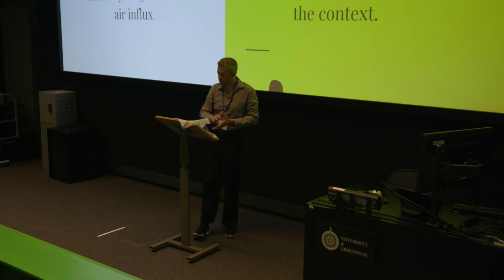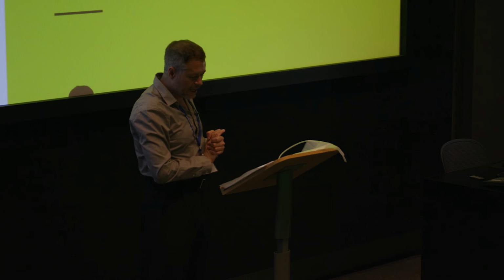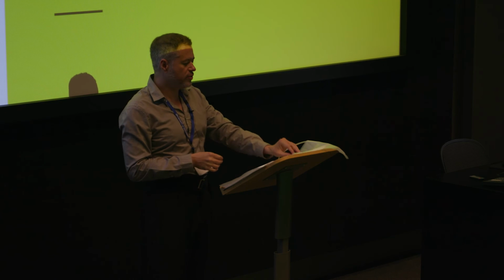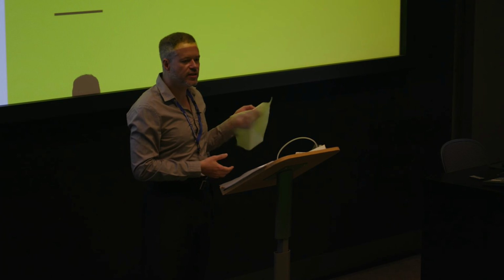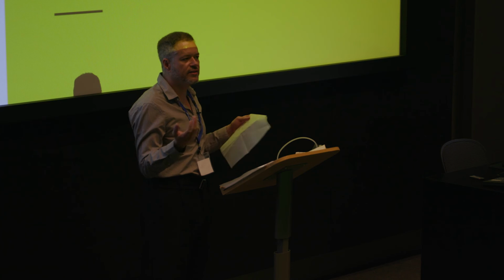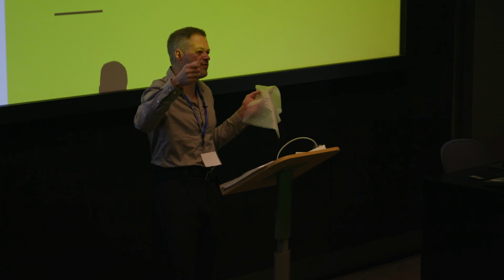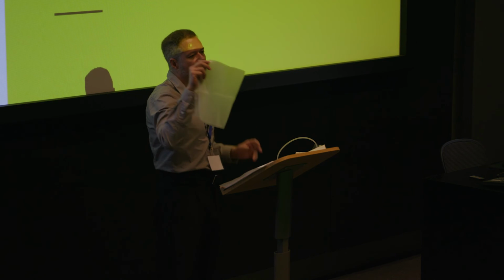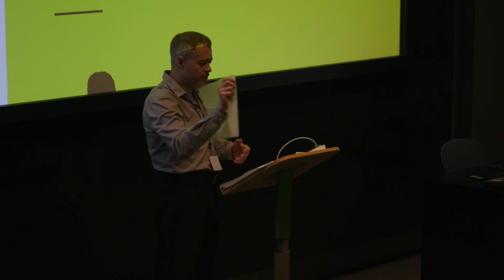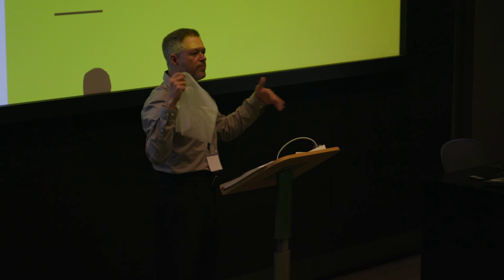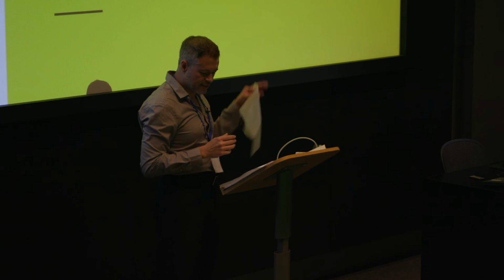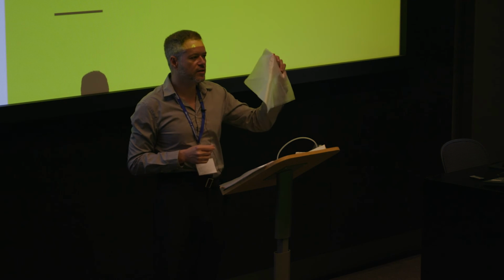It works pretty well. Even if you don't have a 3D printer, you can use a heated element, for example, a soldering iron if you regulate the temperature very low, and you can create these geometries by hand. So if you are in a context that doesn't have many resources, this technique would be best.